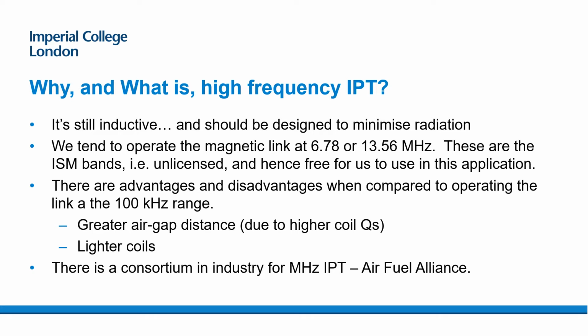So that gives us the opportunity to significantly step up in frequency and try and operate, again, a near field system. We're trying to minimize radiation. It's got to be an inductive system in order to be efficient. We're trying to therefore see whether there might be some advantages of operating at these higher frequencies.